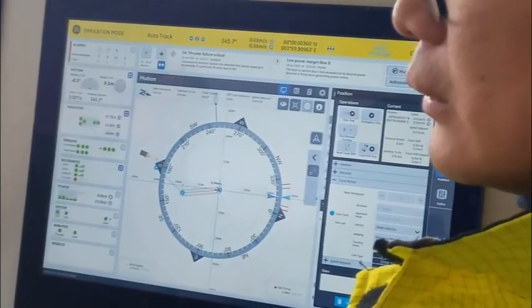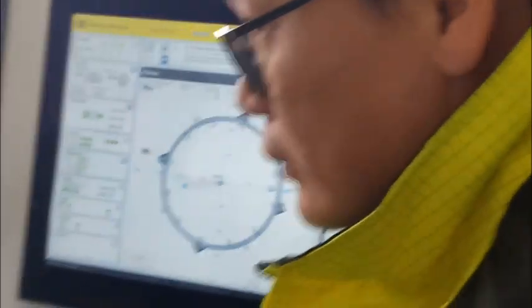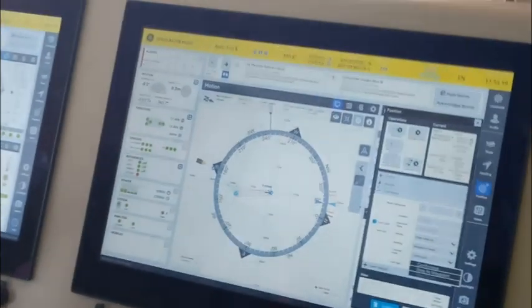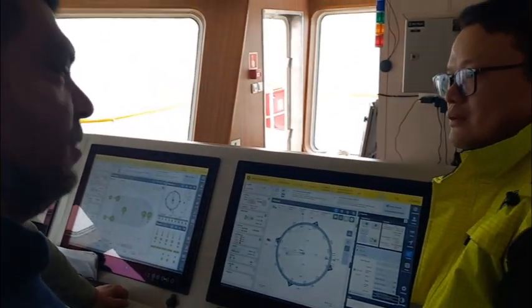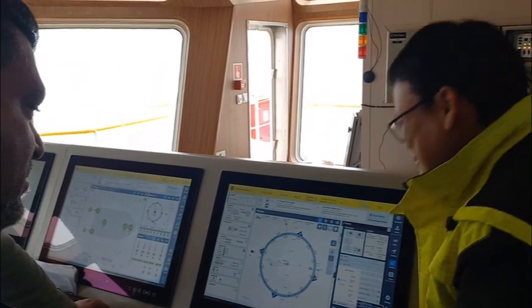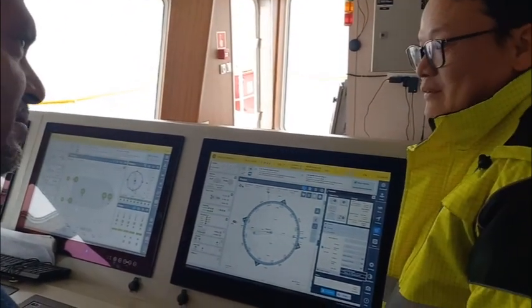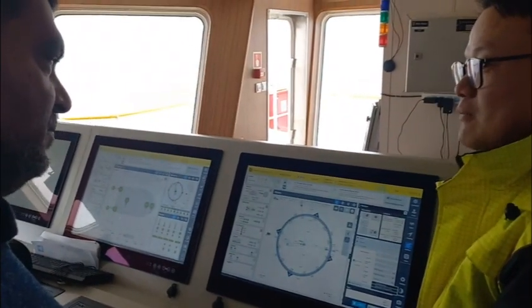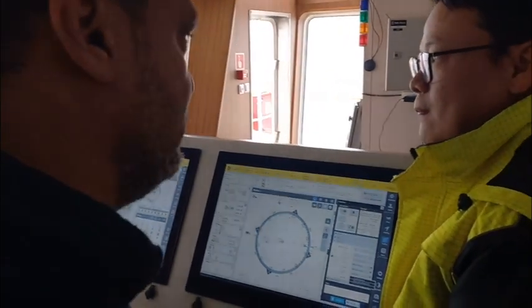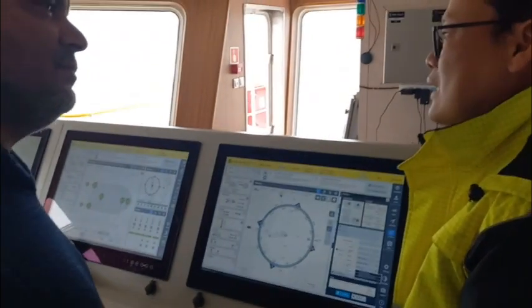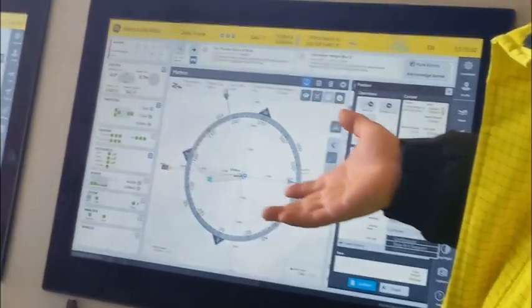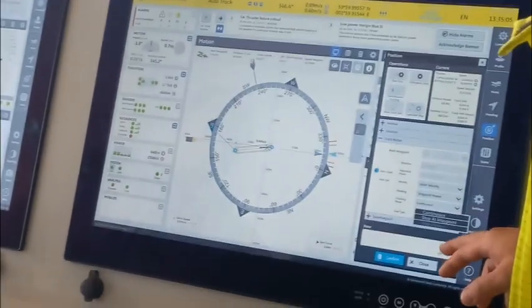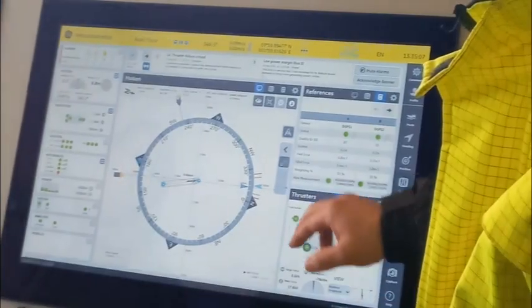I can sail with the DP mode, right? Sorry? I can sail with the DP mode, make a setting from here to the Middle East. You can, but why would you do that? I want to, for training. Sailing with DP mode or auto track mode? Auto track, I put waypoints. Well, that's not what auto track is designed for. Auto track is for slow speed. Slow speed, okay. Sailing is high speed. I'm doing it all the time. Okay.